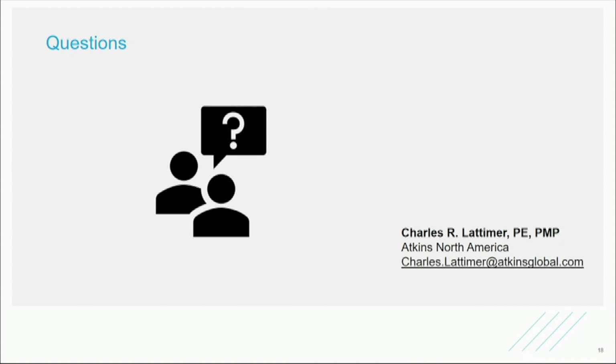So that's a good question. So the way ATSPM incorporates it is there is something called a pedestrian delay, that metric that's in there, but that assumes that it's going to be the same ped time. There would probably have to be a new enumeration created, because it sounds like you'd have different kinds of PED calls then. They'd have to pretty much expand that enumeration to be able to differentiate between what those PED calls were. But by doing that, you could then probably have a good mix of what my population looks like of pedestrians. So that's a very interesting idea.